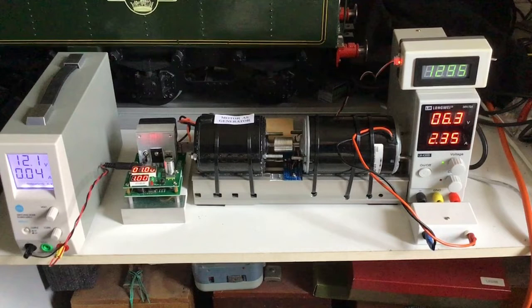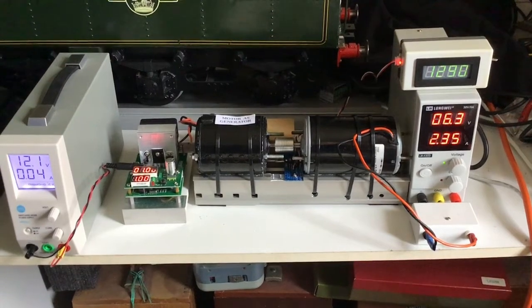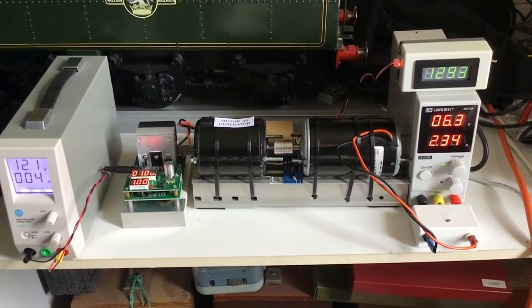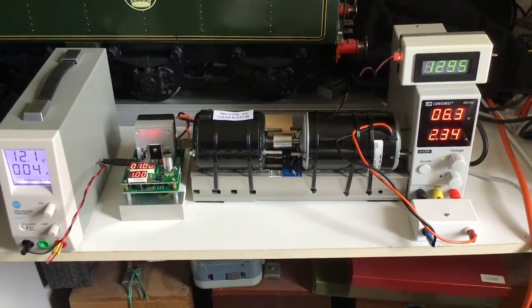The plan is to apply an additional constant torque load to simulate an incline. To provide this load, the 150 watt Fasco will be used to cause dynamic braking. If I simply fed its Vg into a resistor, the braking would reduce as the speed falls. To provide a more realistic situation, I've used an electronic load, set to supply a reasonably heavy stabilized 1 amp load, irrespective of the value of Vg.